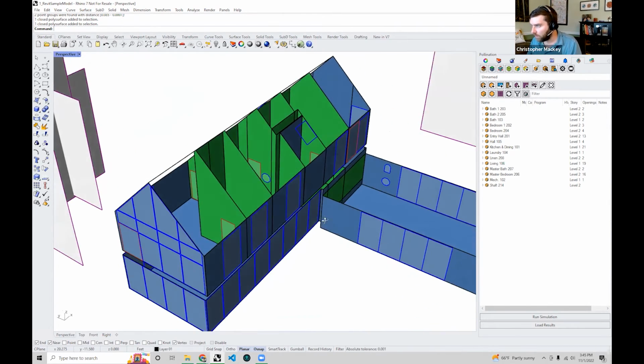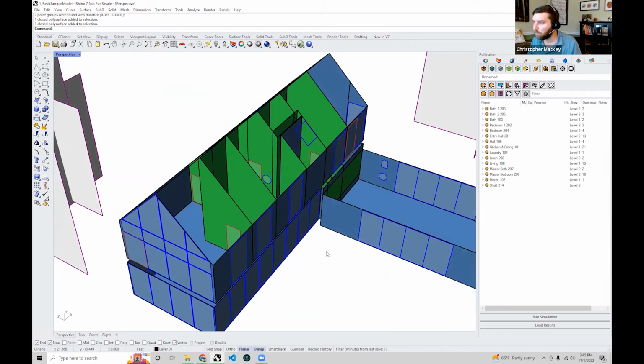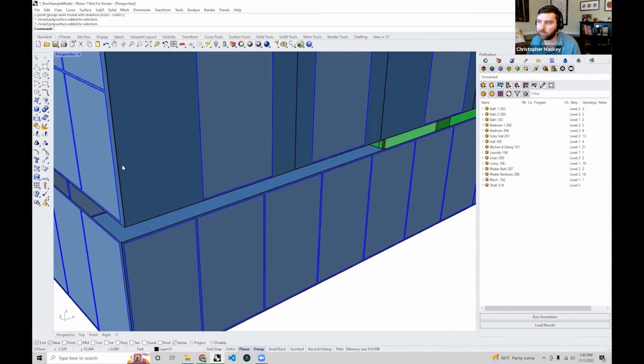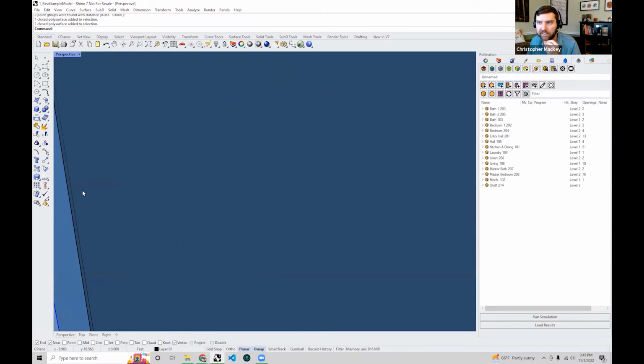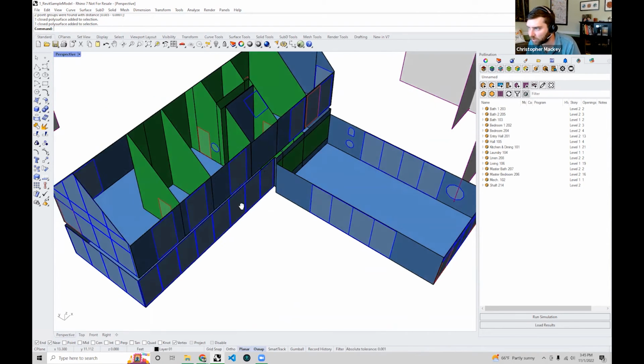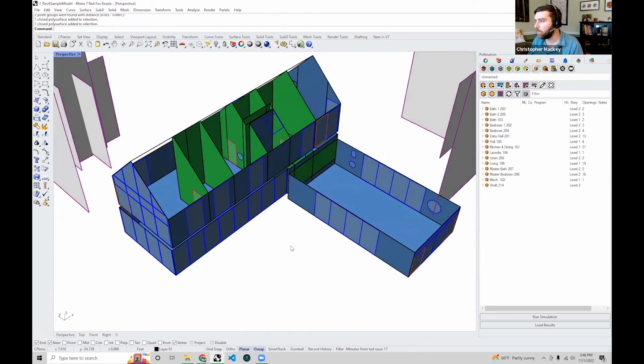So, all right, let's go down the list here and start to fix up some of these things. Maybe first things first, let me try and fix this little sliver face. At the same time, I'm going to use a single command that's going to get rid of this sliver face, and it's going to reset all the boundary conditions so that I'll be in a good place to resolve adjacency after I fix all this geometry up here. That one command that does all this together is called PO rebuild rooms.